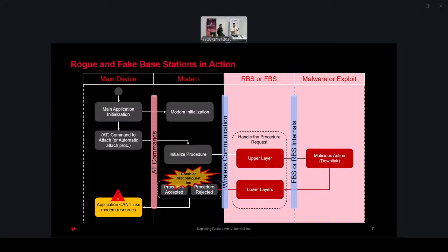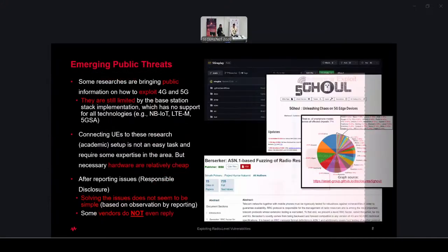Do you remember the state machine? So it moves to a wrong state. And in some cases, or most of them, the application or the controller cannot connect to the modem through AT commands, or it stops working properly, or starts to do wrong things, mainly. So that is the key point, the way to discover these problems.